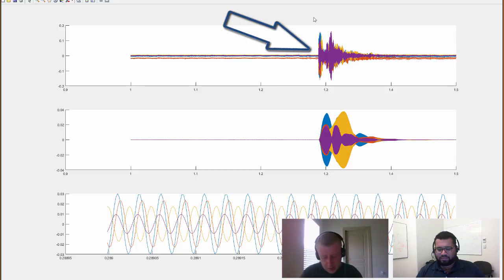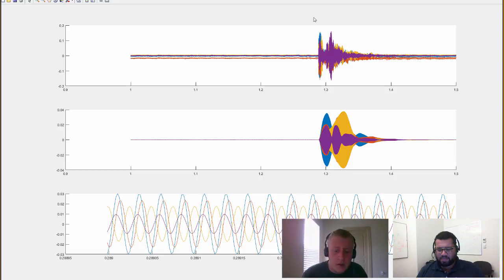That's because the data after that point is most likely the result of a reflection of something in the environment, whether it be the surface of the water, the vehicle, anything else. And we can consider that data to be corrupted. Whenever you have a reflection, you're going to induce a phase shift into your data, and then that entire equation we have based on phase shifts breaks down, and you're going to get inaccurate bearings.